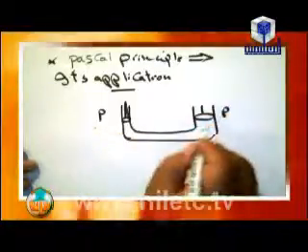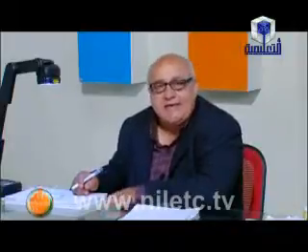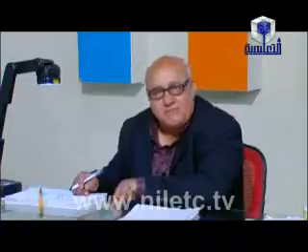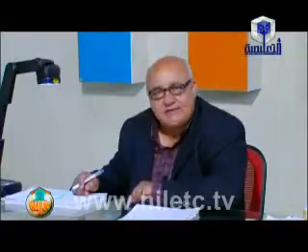So the pressure acting on the small piston is equal to the pressure acting on the large piston, according to Pascal's principle. But the force acting on the large piston is greater than the force acting on the small piston, so the ratio between them is more than 1 if we start with the large piston. But if we start with the force acting on the small piston, the ratio will be smaller than 1.